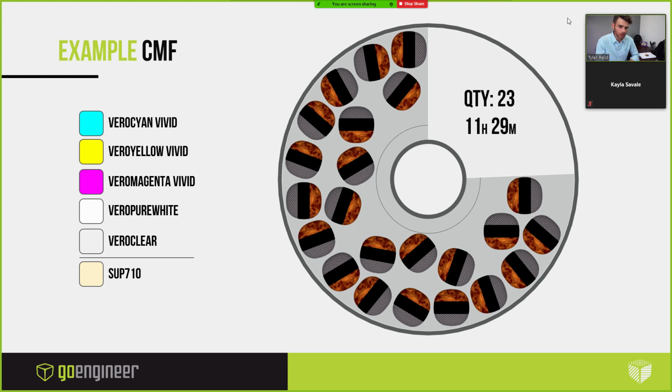The 5 core materials, you have some flexibility in what you might load up. So in a scenario like this, where we have some wood grain, we have some carbon fiber, and we want a very shiny finish on this, I might choose a scheme like this, where I have cyan, yellow, and magenta, and white. So really I have 4 colors and then clear.